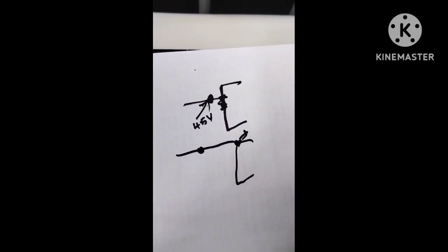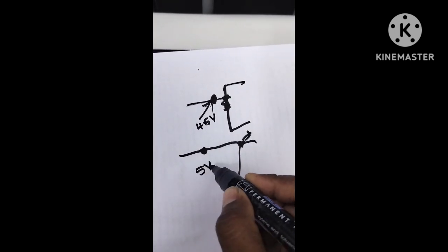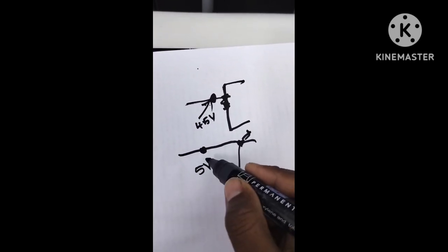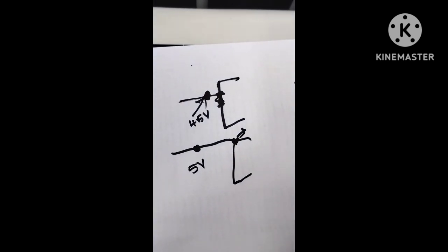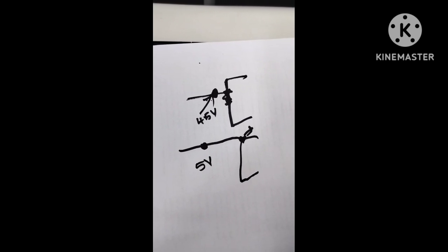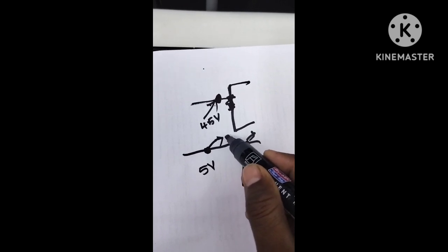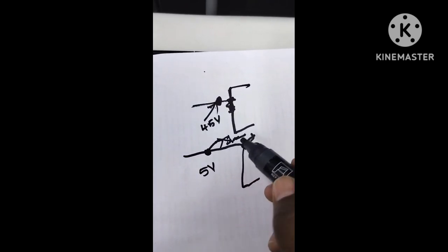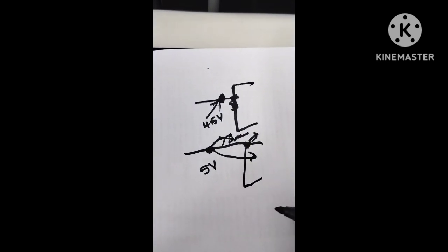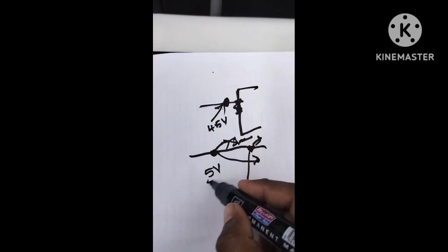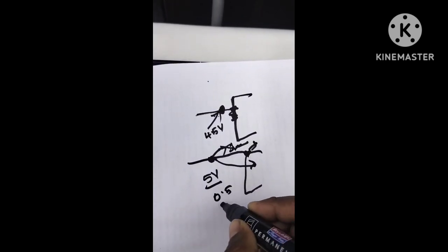Anywhere on this engine body, I short this temperature sensor wire. You may have a doubt that this has a 5 volt reference, and if you short out this 5 volt reference, the engine computer will be affected and it could lead to big damage. But the thing is, all temperature sensors are designed for shorting purposes only. No issue when we short this 5 volt reference to the body. When the resistance is low, this 5 volt will never be 5 volt. It comes to 0.5 volt, 1 volt, like that.